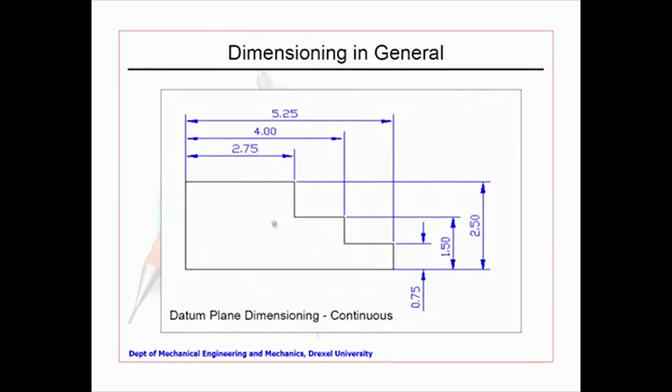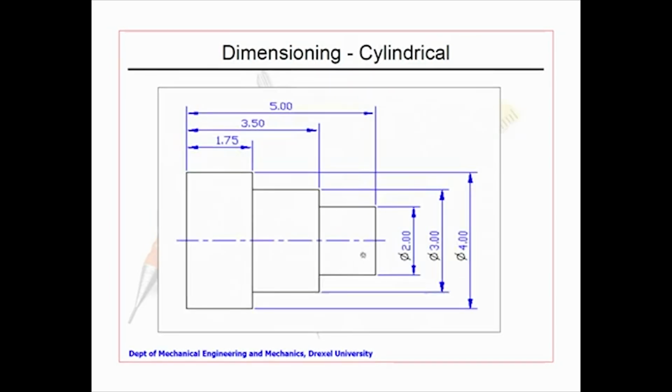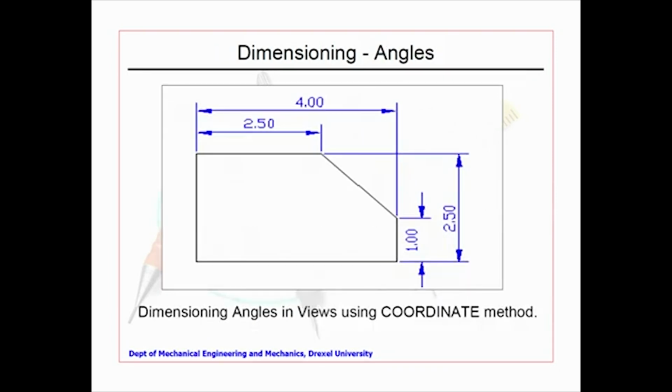While this could be a section view, half section view and all this, invariably these cylindrical parts are all mentioned with the diameter symbol. Only in rare cases the word dia is written, otherwise depending on the precision you require, 2 digits are shown there. This looks like auto generated in some CAD package. As is mentioned, it is AutoCAD in the beginning, probably it is done like this.